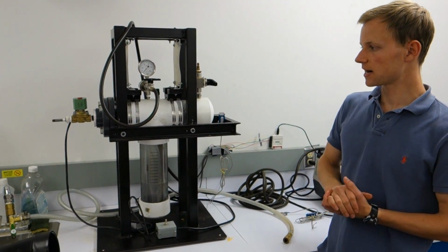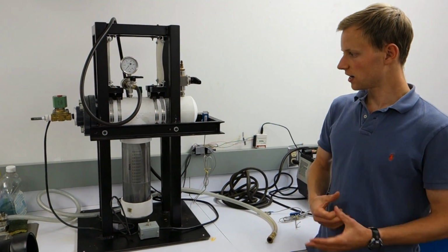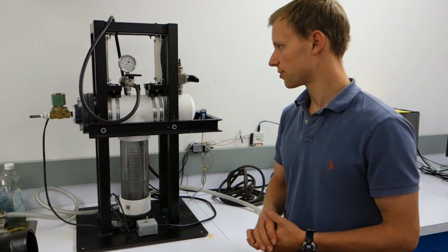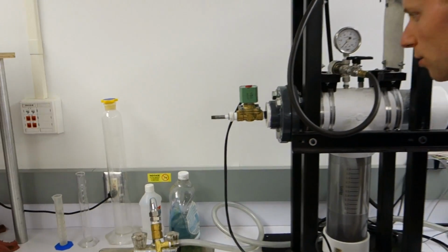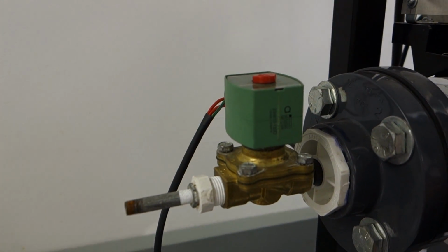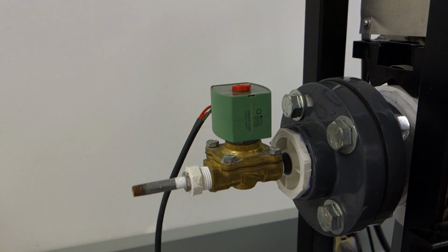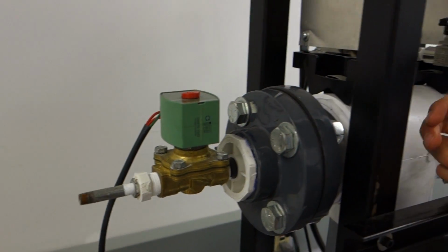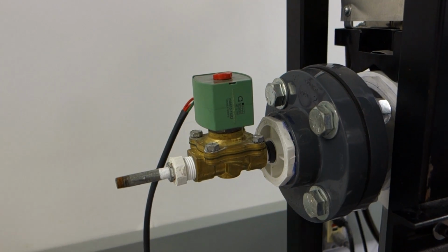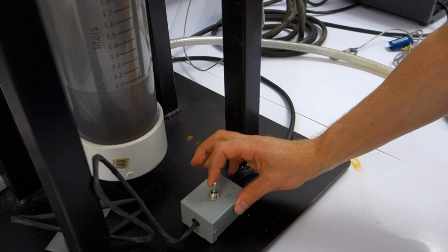So let's look at the system and identify all the components that we can and explain them. So what do you see in this whole setup? We could talk about every component on its own. Working left to right here, we've got this green box. This is a solenoid. It is a valve, so when the valve is closed, the system will be sealed off and we can pressurize air inside of it. When we open it up, the pressurized air will drive water out of the nozzle, and we can close and open the solenoid valve. If you come down here to the switch box, closed, open.